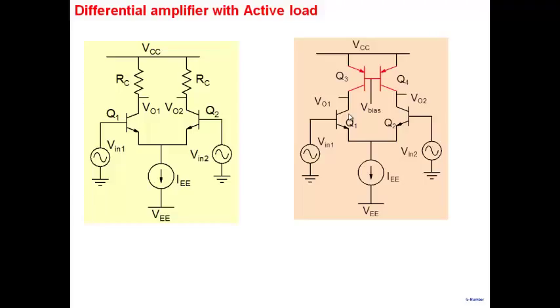If they're identical, then it's fine. But in practice, you will never get two identical voltage sources. If one of them is 1.5 and the other one is 1.55, and you connect two voltage sources in parallel, one of the sources will fail. The effective voltage across the two nodes will be either 1.5 or 1.55. One of the two sources will fail.